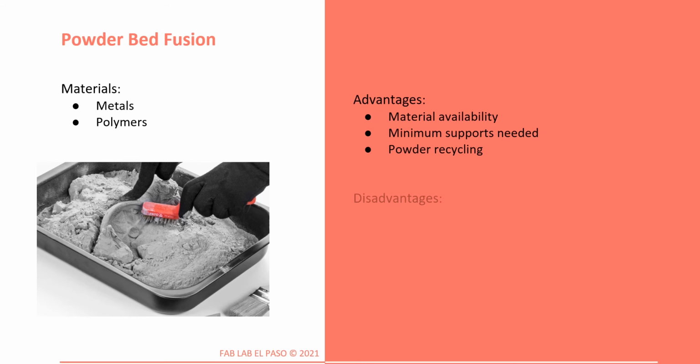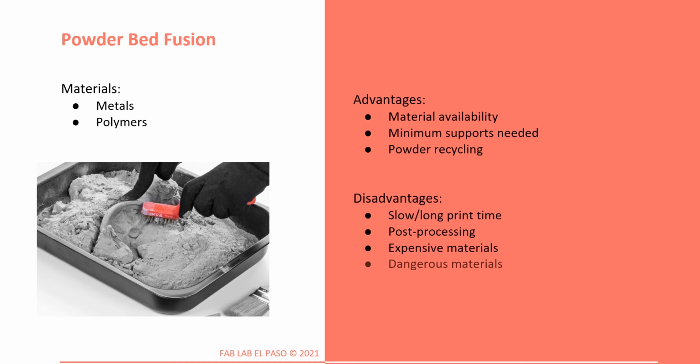Some disadvantages of powder bed fusion include slow, long print times, as well as lengthy post-processing techniques. Also, powdered materials are expensive and can be dangerous to work with, so they do require special safety measures and PPE.